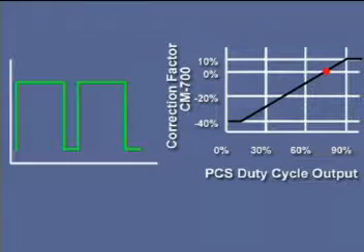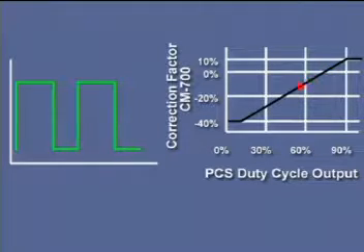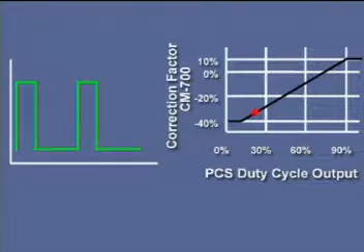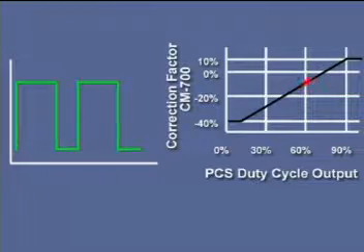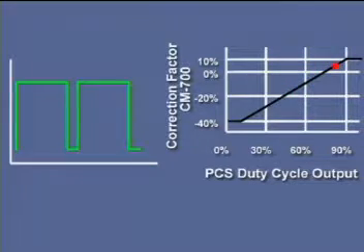A 74% duty cycle is interpreted as a null bias request by the CM700. In other words, at 74% duty cycle, the CM700 provides no speed correction from its base speed set point. While this signal is capable of changing the engine speed from -40 to +10% of rated speed, the CM700 limits any change to -10 to +10%.